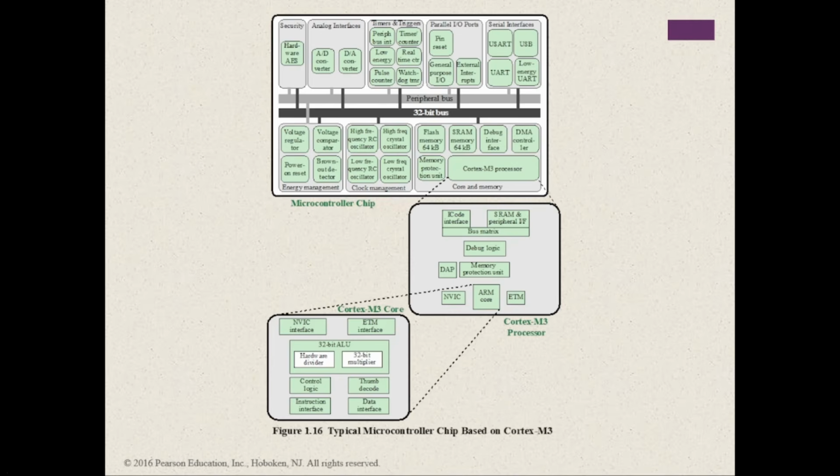neither in the Cortex M3 processor nor in the microcontroller as a whole, which plays an important role if the code or data resides in external memory. Though the number of cycles to read the instruction or data varies depending on cache hit or miss, the cache greatly improves the performance when external memory is used. Such overhead is not needed for a microcontroller.